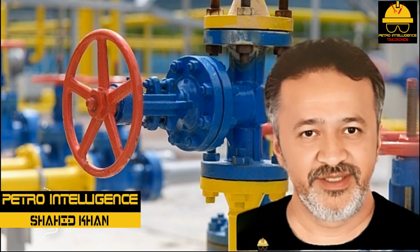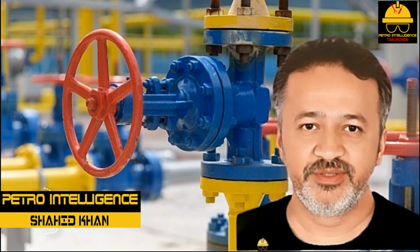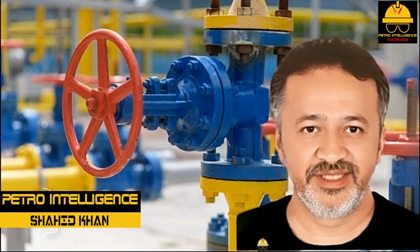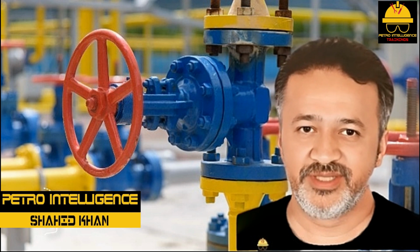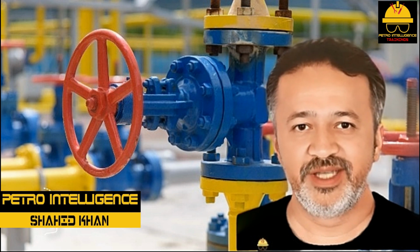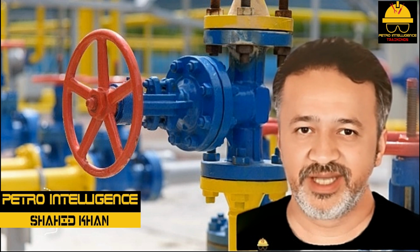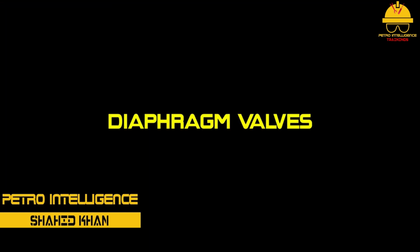A plug valve should never be used for throttling. Excessive wear will result if a plug valve is throttled, and the valve's ability to obtain a positive seal will be jeopardized. Most plug valves should be limited to temperatures under 480 degrees Fahrenheit or 248.9 degrees Celsius. Higher temperatures displace the grease and cause the plug and valve body to seize or warp.